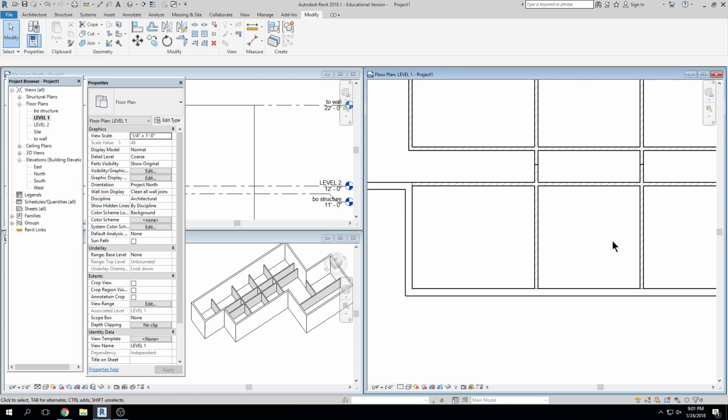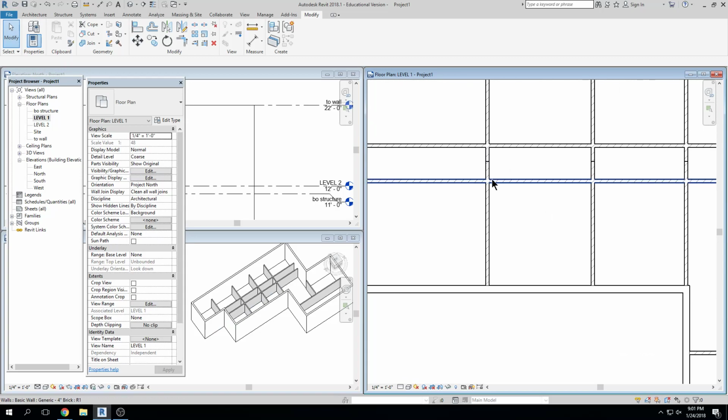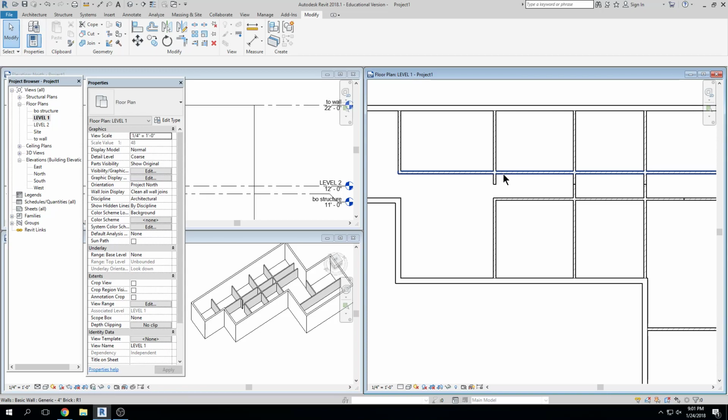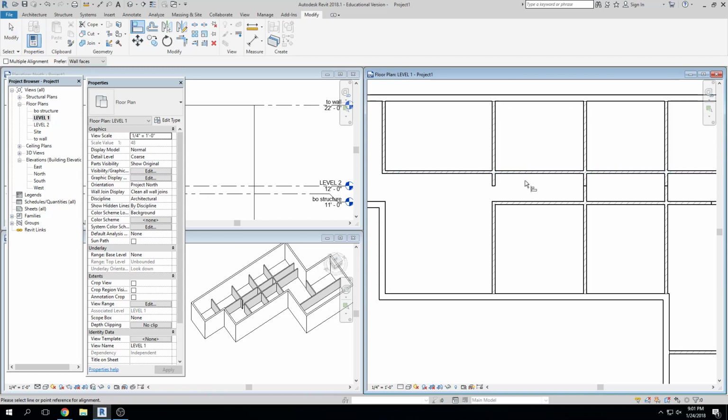Okay. But, you know, I'm probably not going to get the cleanest trim, just trimming all these, because this wall will be affected, right? If I go TR, trim, click, click, do you see how it kind of kills the rest of that? That's okay for what we're doing right now. But I could also align, AL, click, click, right?